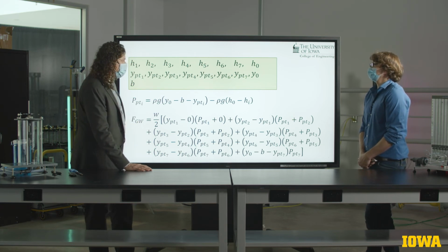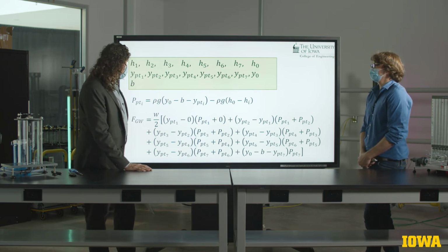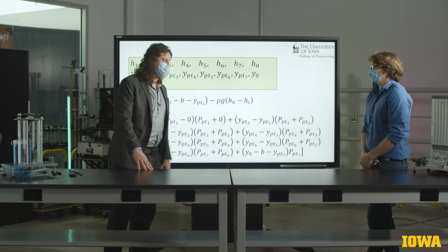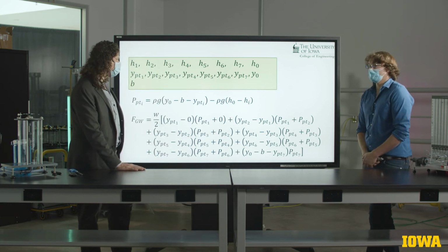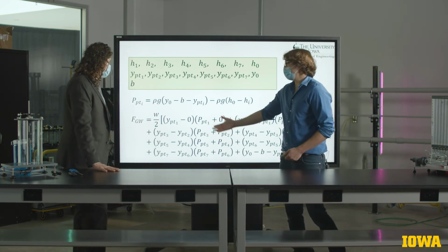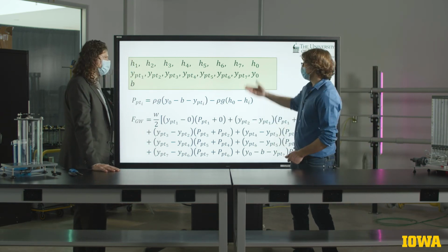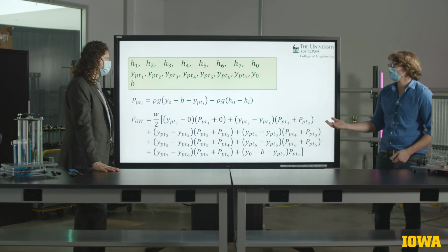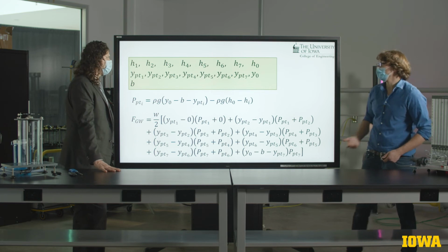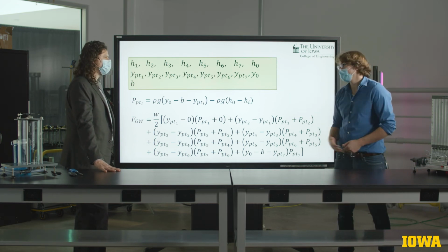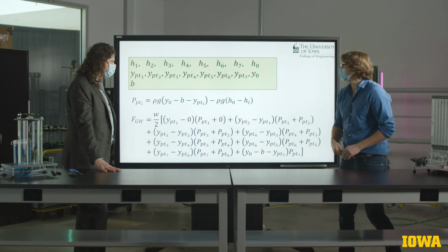So with this equation, we will be able to determine how precise a measurement of force we can make by determining how precise our measurements of pressures are. Right. As with any data reduction equation, if we take the partial derivative of this result with respect to one of our measured variables, then we'll get a sensitivity coefficient, which we can then use to propagate elemental uncertainties in, for example, our piezometer water column heights into our final solution here.